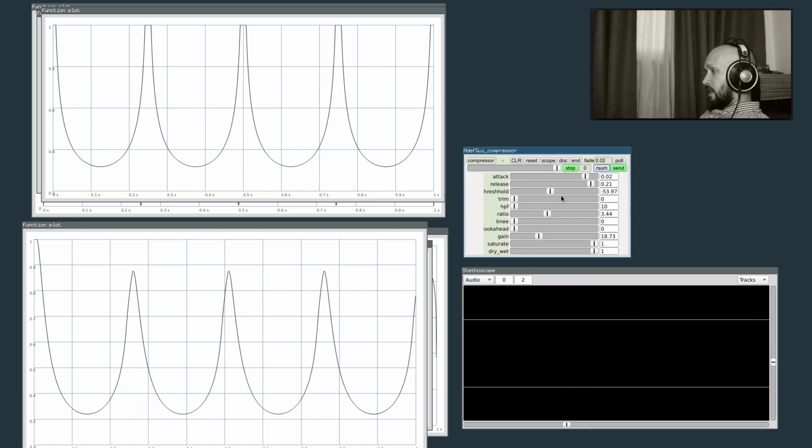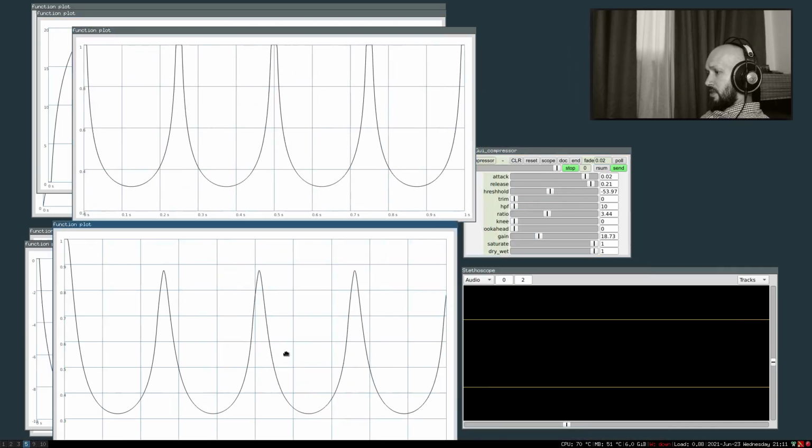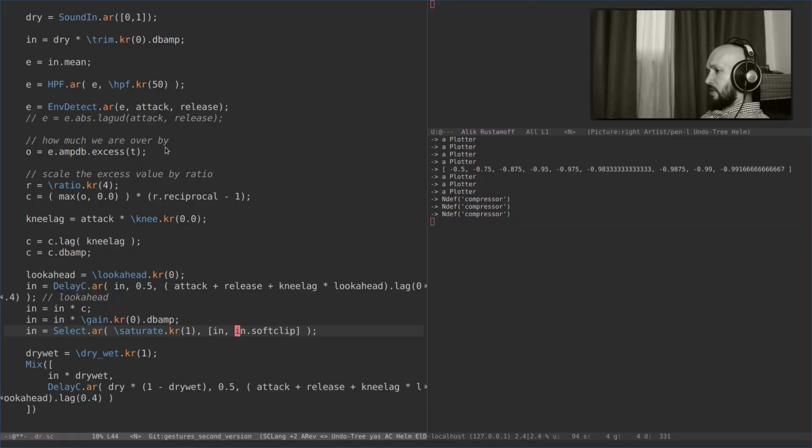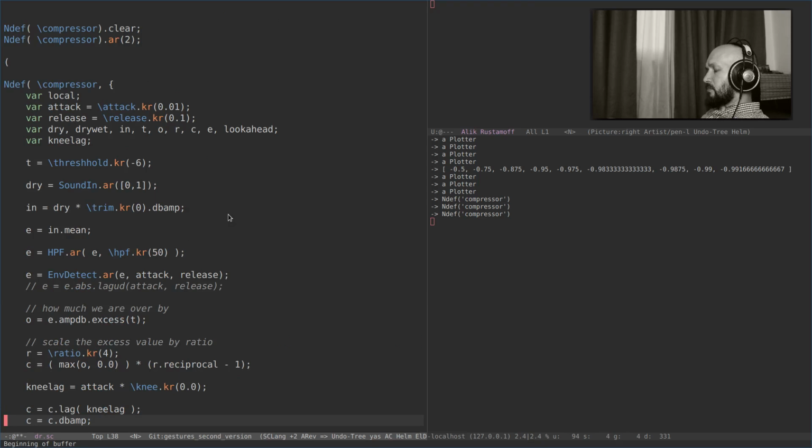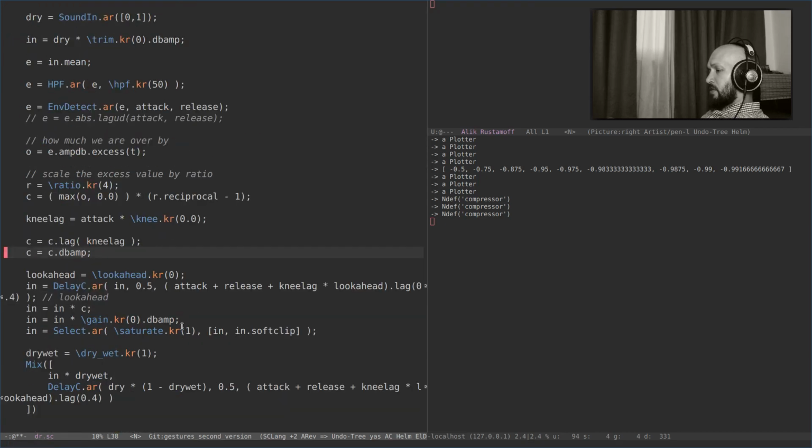How do we fight that then? One of the simplest things is to use inertialess compression. Yeah, the thing depicted here, these averaged signals, can also be called compression with inertia. But this soft clip thing, nonlinear wave shaping, yeah, another way of nonlinear wave shaping, can be implemented just by indexing into a table. The Shaper unit generator in SuperCollider does that.